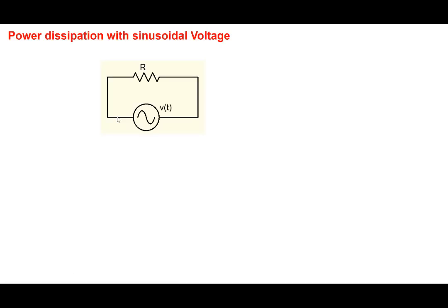All right, coming back, we've seen how to calculate voltages and currents. Let's look at power dissipation. We know that if I take a voltage source and connect it to a resistor, the power in the resistor is V squared by R, so v(t) squared by R. Most of the time we are not interested in the instantaneous value of power. What we want to know is the average power dissipated. So when we talk about average, for a continuous signal, we take an average in the form of 1 over T, integral from 0 to T, of v squared by R times dt. We do the averaging by performing this integral.